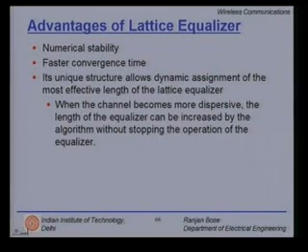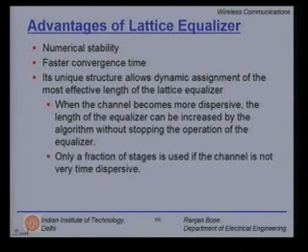When the channel becomes more dispersive, right, the mobile enters a densely packed urban environment, the length of the equalizer can be increased by the algorithm without stopping the operation of the equalizer. On the other hand, only a fraction of stages is used if the channel is not very time dispersive.